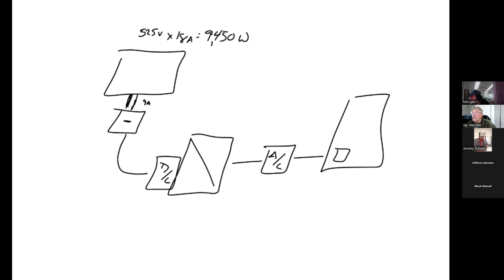So if they're high temperature, great. But if they're low temperature, that becomes the weak part of the system. So always assume the lowest. So 12 gauge wire, we're going to assume 20 amps. That's what it can handle. Okay, everybody with me so far?